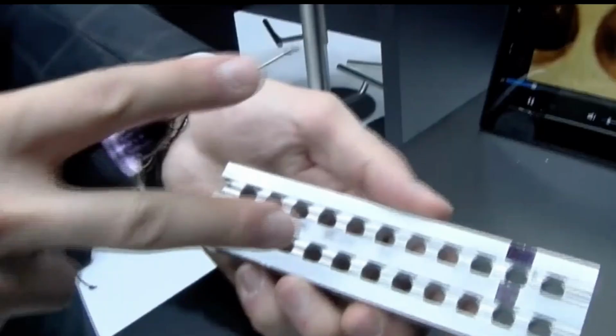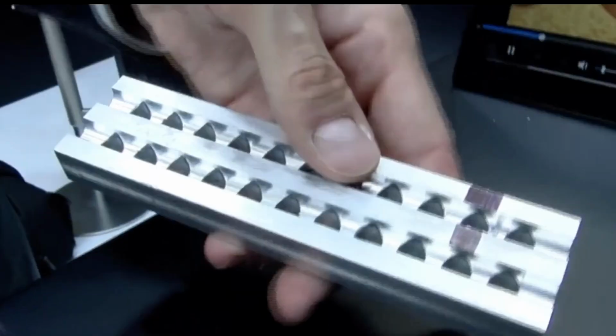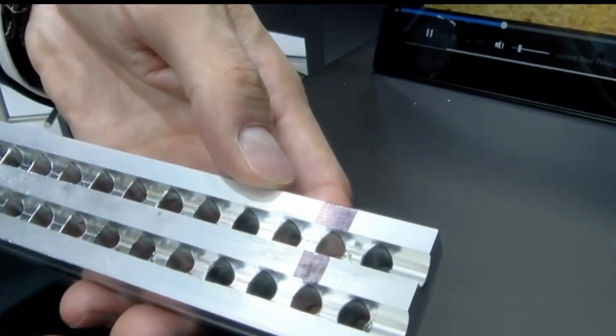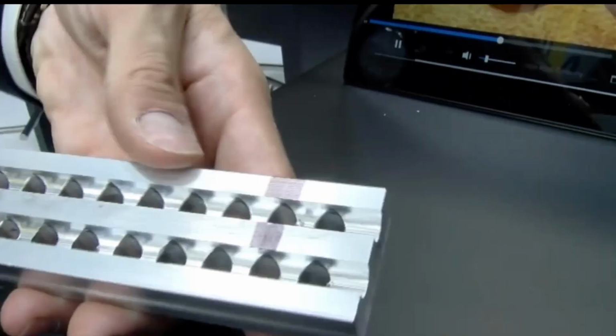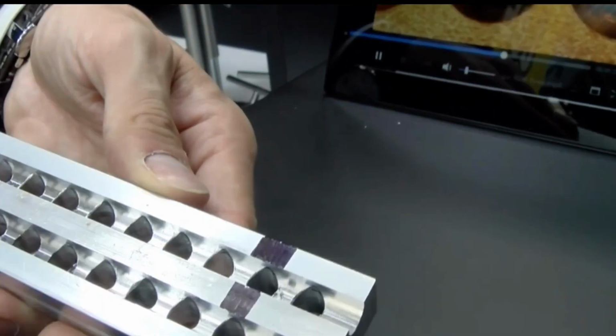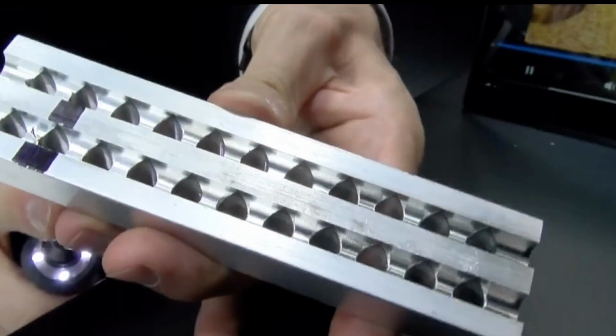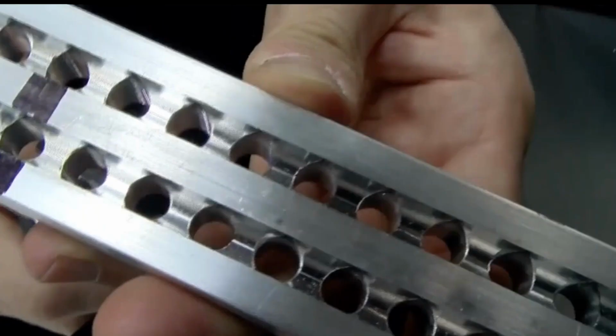So here we have an example of a hydraulic manifold. Essentially, this is your cross hole. This is basically a manifold that was cut in half. And you have a series of cross holes that are drilled into the main bore, and that's where you're developing your burr. So we can try to put it in this way so you can see it, and I'll deburr it from the back. So I enter the hole.